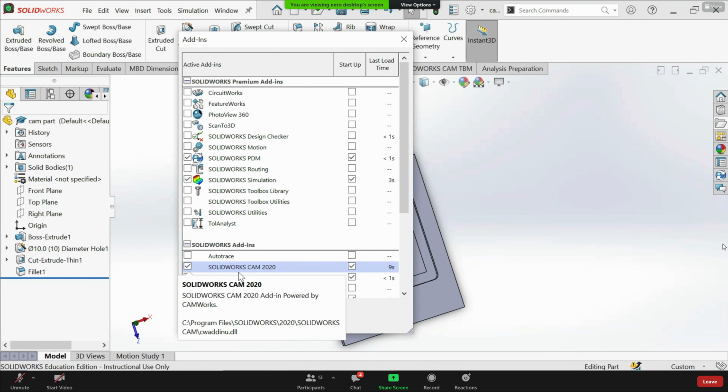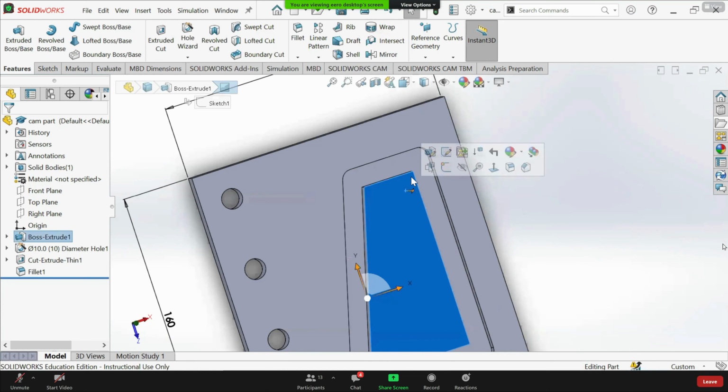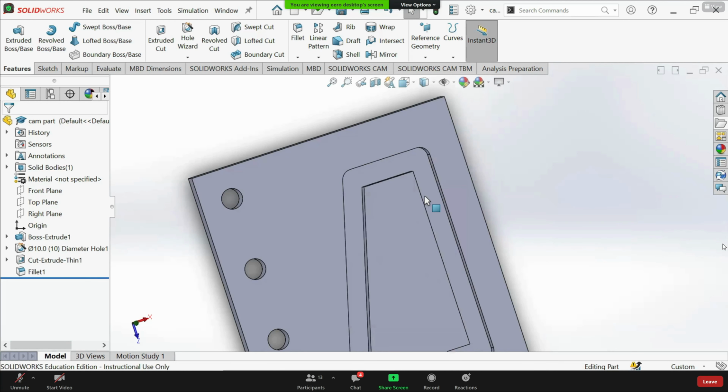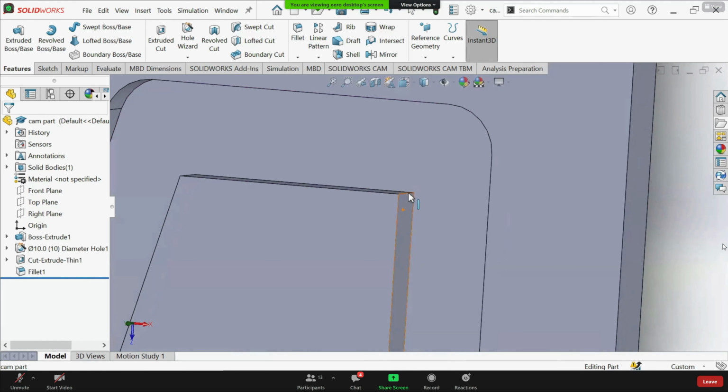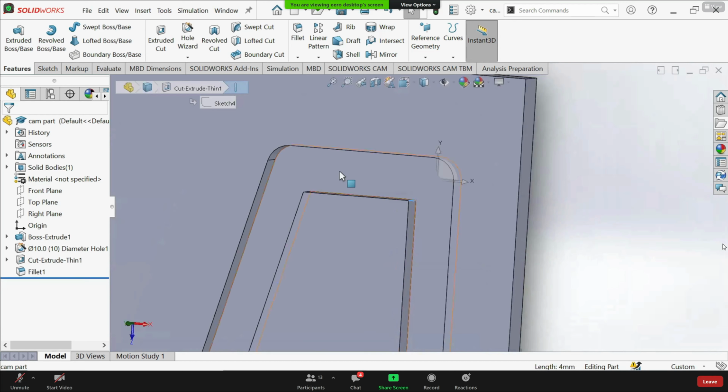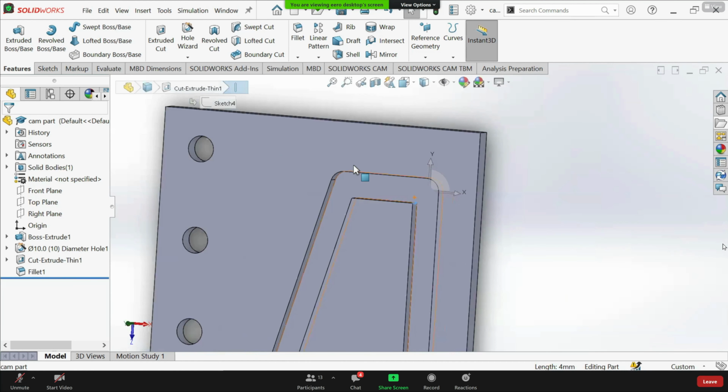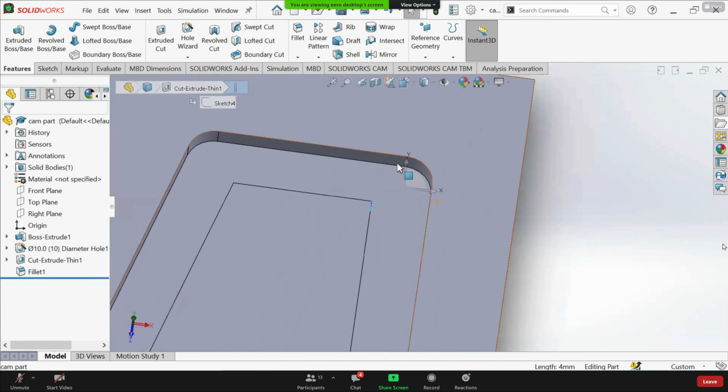Sorry for interrupting you, but what about inside corners of the groove? Shouldn't they be filleted? Like I said, it's not a problem to machine such a corner. Oh, so sorry, I just missed it. So we'll leave the inside corner sharp. This can be sharp. It's not a problem to machine an inside sharp corner. This kind of outside sharp corner is difficult. In this case, the outside corner is difficult. Okay, clear. Thank you.